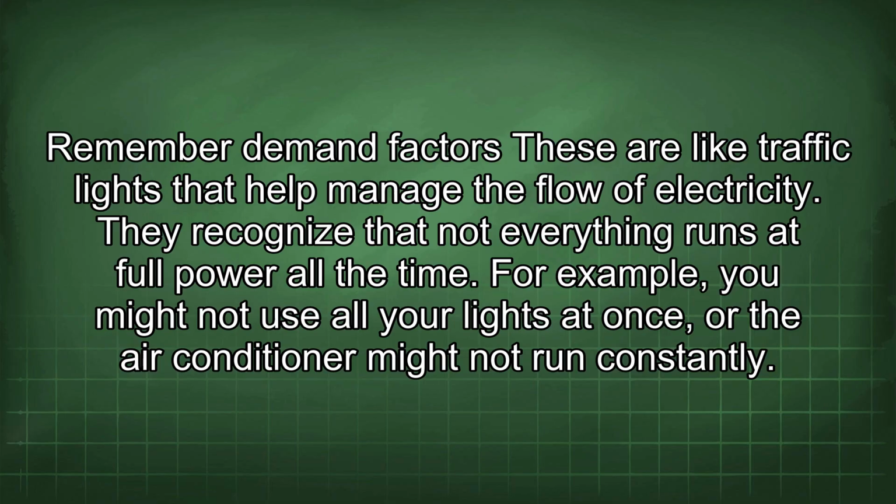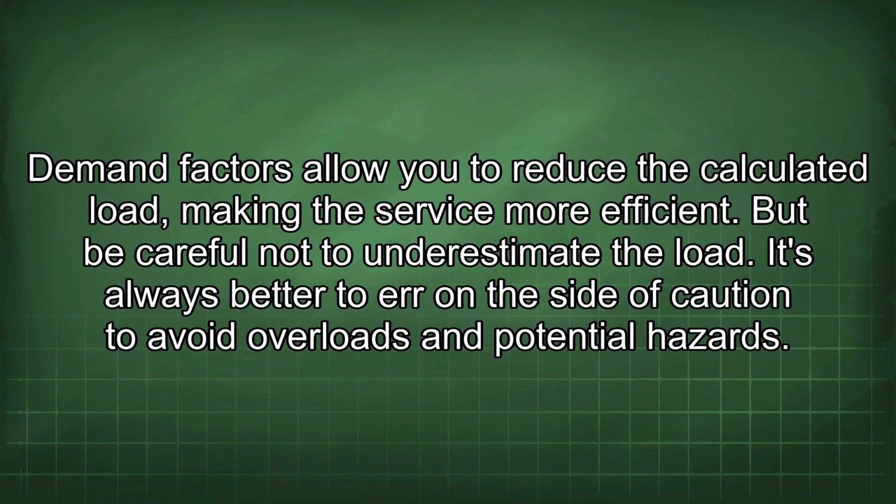Remember demand factors: these are like traffic lights that help manage the flow of electricity. They recognize that not everything runs at full power all the time. For example, you might not use all your lights at once, or the air conditioner might not run constantly. Demand factors allow you to reduce the calculated load, making the service more efficient. But be careful not to underestimate the load. It's always better to err on the side of caution to avoid overloads and potential hazards.